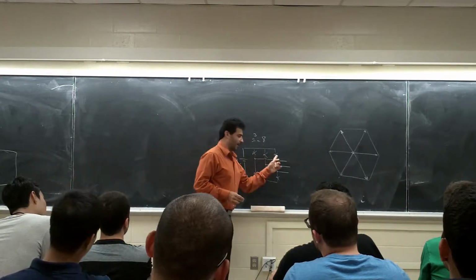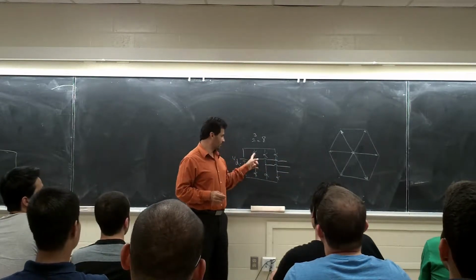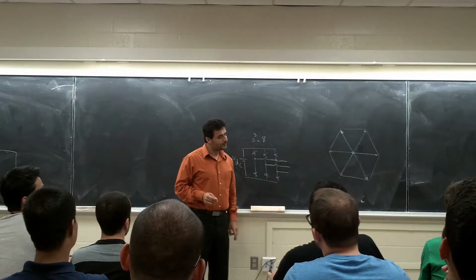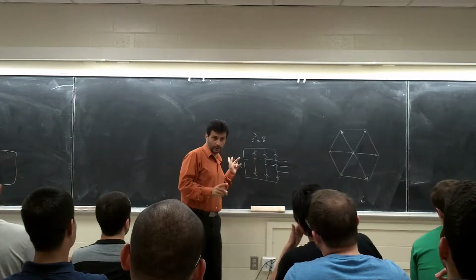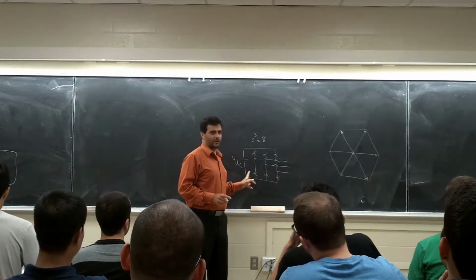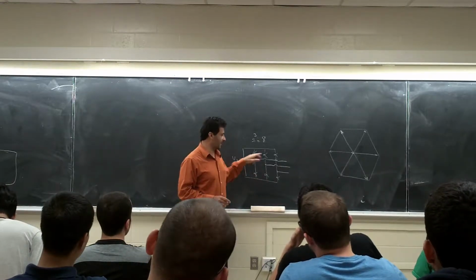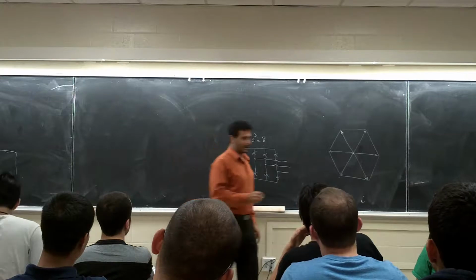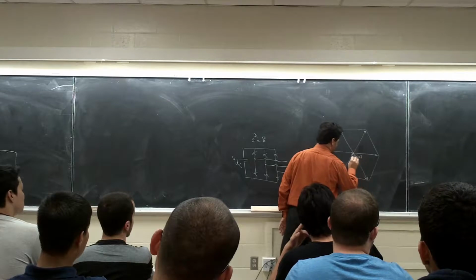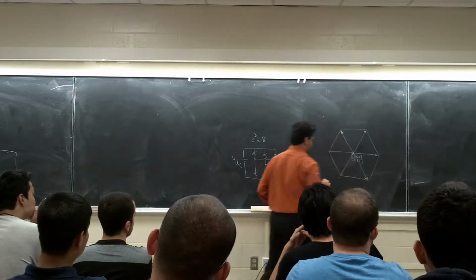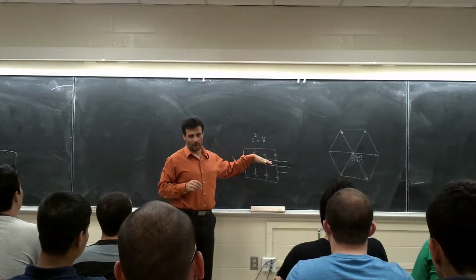When these 3 are on, how much is the output voltage? 0. Why? They're shorted, right? Output, not here, I'm saying output voltage. How about when these 3 are 0, and these 3 are on? 0 again. They call this case and this case the zero vectors, V0. It's going to be 0,0,0 or 1,1,1. This is basically the status of these switches: 1 means they are on, 0 means they are off.